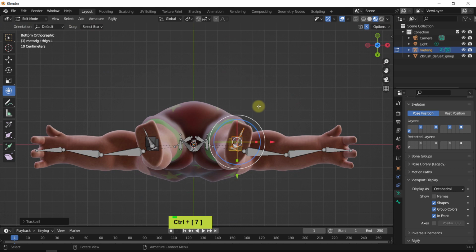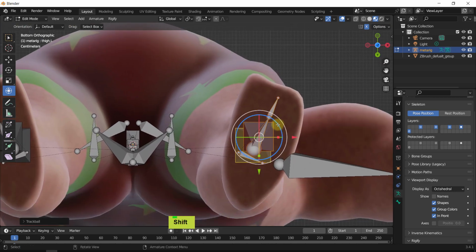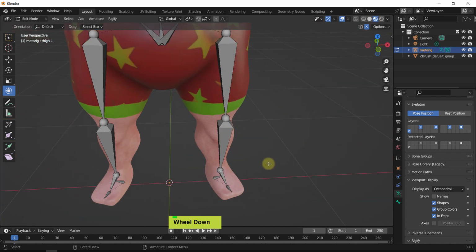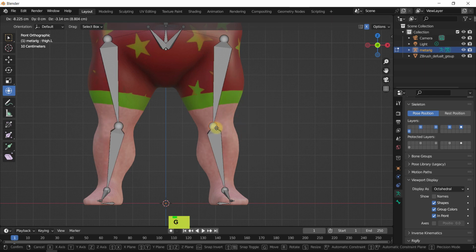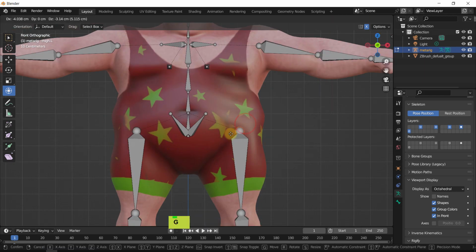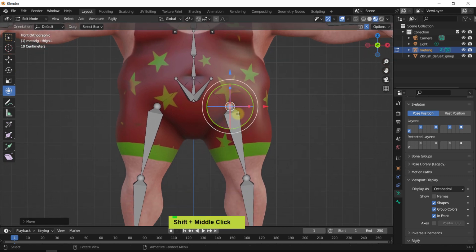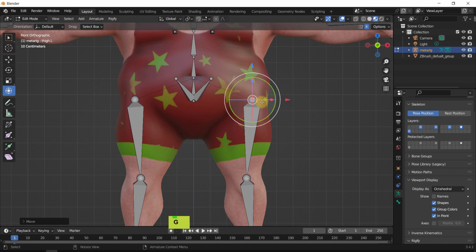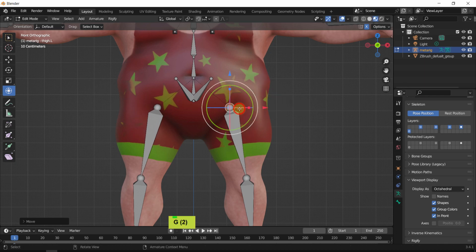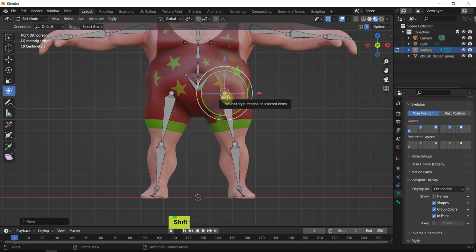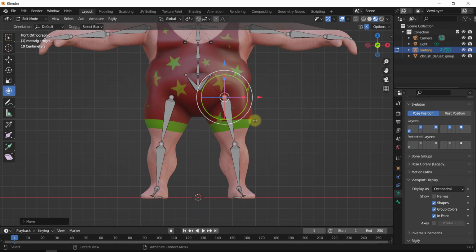And going to the bottom view, Control numpad 7, and looking at the orientation, which one looks promising. Alright, let me go to the front viewport, selecting this knee in the front. The hip sockets. Be careful, don't leave these outside, because we are following anatomy and not only the visuals, so that should be somewhere there. If you place it in an odd position, you will see the effect in deformation.